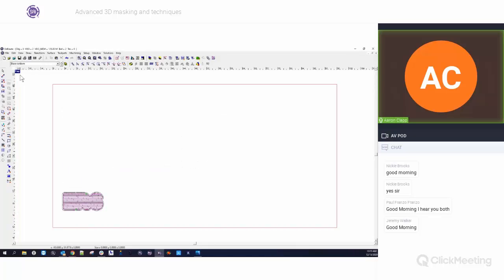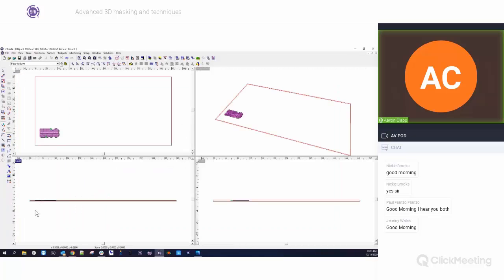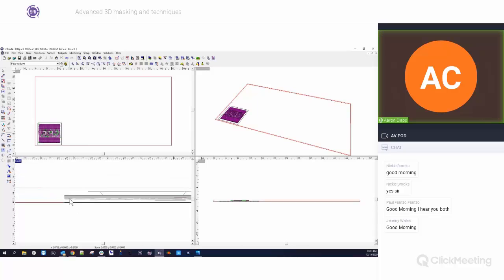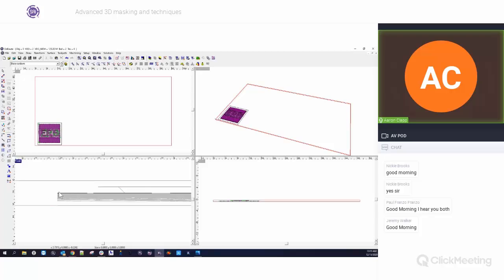And what I've done is, if you look at it from the side view, and I turn on all layers, I've moved my relief all the way to the bottom of the plate. And my relief is, I think, 0.5 inches tall. So I've got 0.5 inches of relief and 0.5 inches of material above that. And so that's how I get this all the way at the bottom.